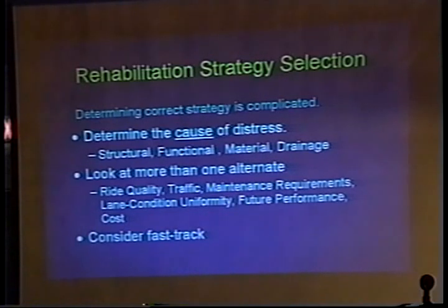You use the heat of hydration method in the maturity process to tell you what your anticipated strength gain is at a certain point in time, using actual field-measured probes in the pavement itself. It's a relatively inexpensive method, and if some of you go to the Ohio Transportation Engineering Conference in October, there'll be a full session devoted to maturity meter testing and the whole process behind that.